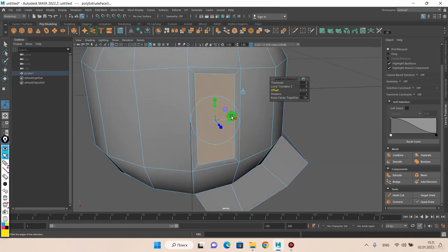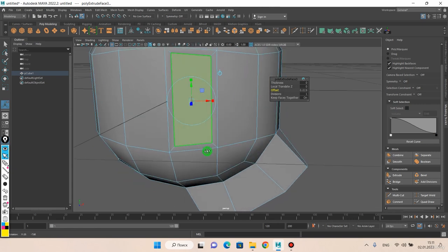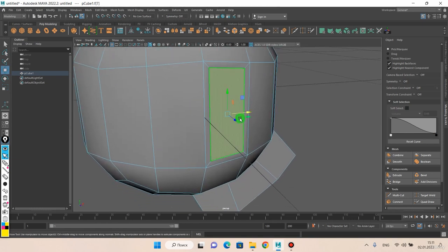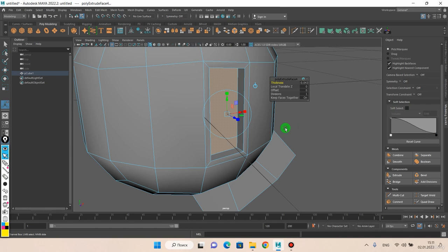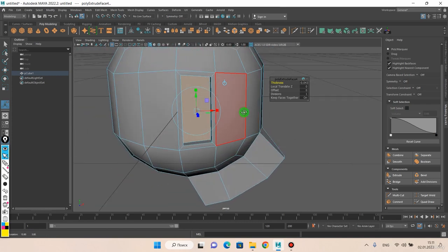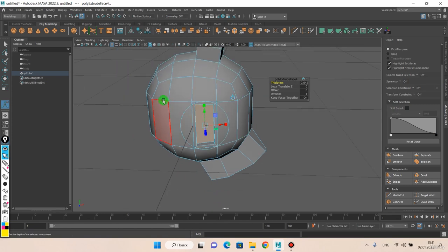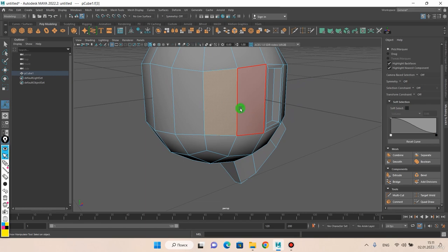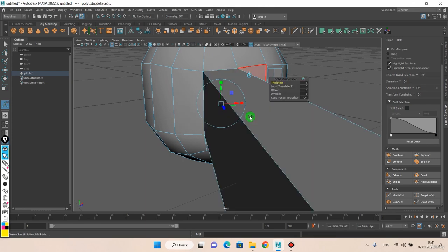That's a classical way to create some components, some structure in our object, and we are getting this rectangular boundary, which we can use too. After we extrude or offset something, we can hit Q or Enter to confirm our extrusion, and we can later move it with the move, rotate, or scale tool.